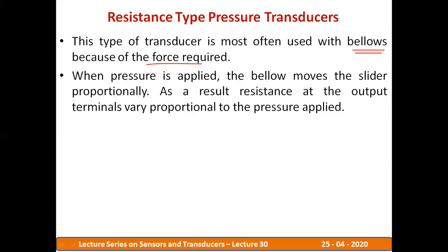So when pressure is applied, the bellow moves the slider proportionally. As a result, what happens? Resistance at the output terminals varies proportionally to the pressure applied. Okay.